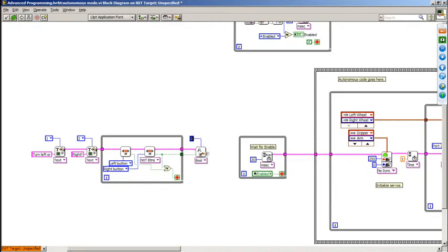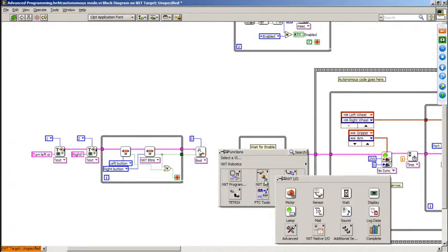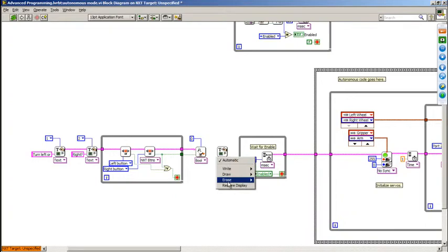So we're okay to go here, but there's one cleanup task we're going to do, which is just to make sure that we clean and restore the NXT display. So again, by going NXT.io, display, and choosing from the polymorphic selector, restore display, wiring everything up, it's going to make sure that once we've made our autonomous selection, whether we're going to go left or right, that it cleans the NXT screen, and then we're ready to go for autonomous. So we're almost completely done here. We've made our selection. Now all we need to do is actually use this value somewhere.